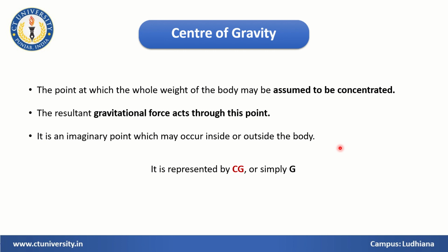So finding that single point is very important because all the forces will be acting through this point. The gravitational forces will be acting through this point, and any other external forces are also very significant. And the location of center of gravity will decide the motion, the bending, or a lot of things that will happen to the product or to the component. So finding this center of gravity is very important.